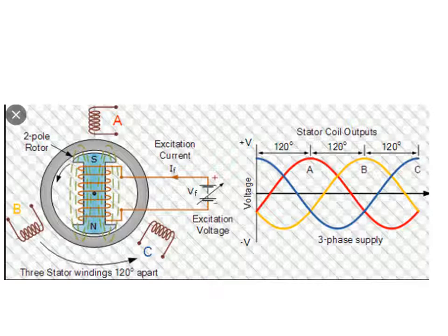Whenever the magnets rotate, they sweep the magnetic field through the conductors, so EMF is generated in the conductors. A conductor that experiences a north pole magnetic field generates a positive EMF, the positive cycle of the EMF. A conductor that experiences a south pole magnetic field generates the EMF in the negative direction. Since the three sets of windings are 120 degrees apart, the EMFs generated across the conductors also have a 120-degree phase difference with each other.